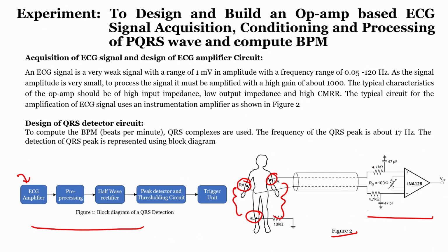The difference between these two signals is our ECG signal, so there are basically two voltage sources in this case. I have to use a proper amplifier or differential circuit to take the difference between these two input sources.